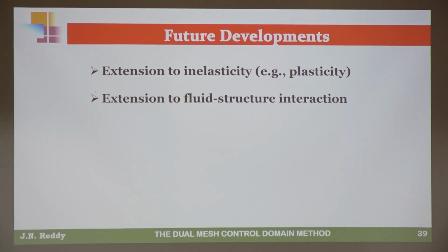And this is where I think we will have a major contribution: fluid structure interaction, because it is a problem where the same method can be used for fluid and solid. Most people who use fluid structure interaction use finite elements for the structure and finite volume for fluids. But the concept of velocity in the two is not the same, because Eulerian description is used for fluid mechanics and Lagrangian description is used for solid mechanics.